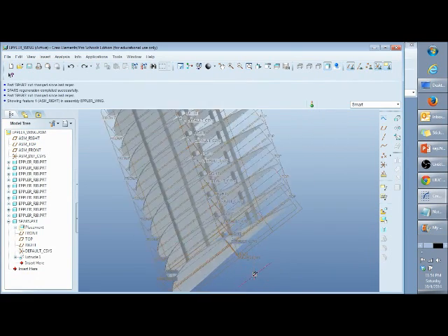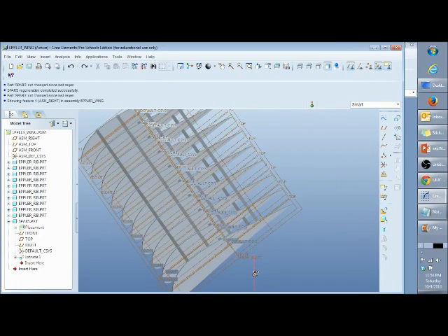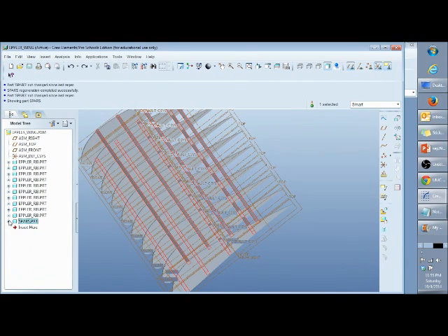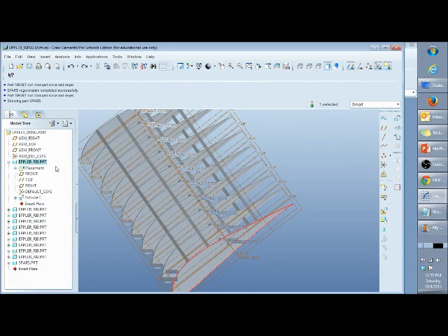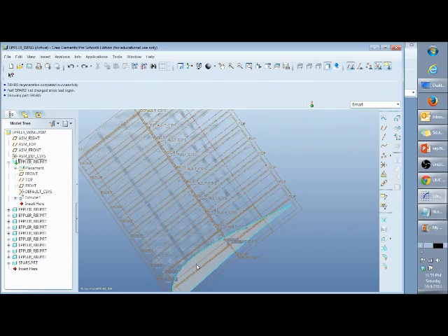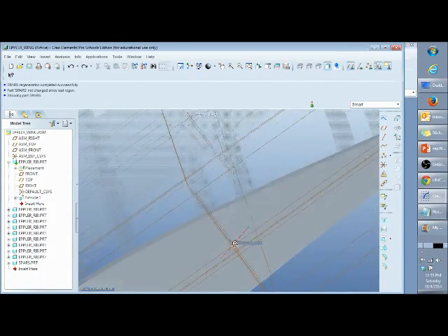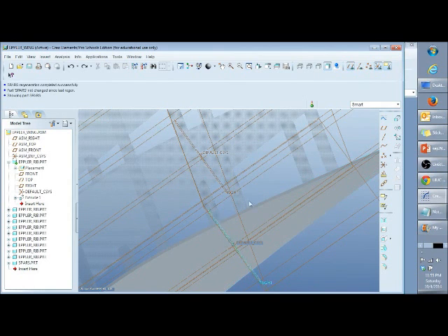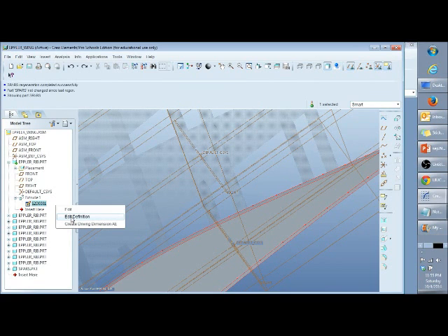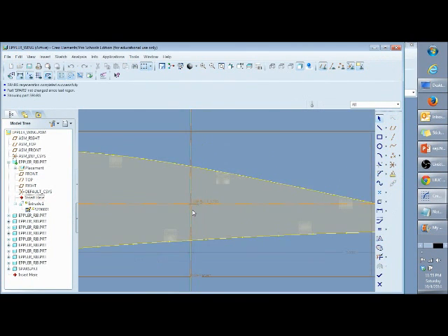I'm going to jump ahead to the next step, then go back and fix what happened before with that whole issue that I just tried to fix that did not work out. What I'm going to do is go into these parts and activate this. I'm going to create the cutouts that will represent the little cutouts you make for the spars, to help align the spars to line up to this back edge. Of course I could just go into Extrude and fix it there, but I think it would be fun to fix it this way. See, definition, troubleshooting, ain't it fun?